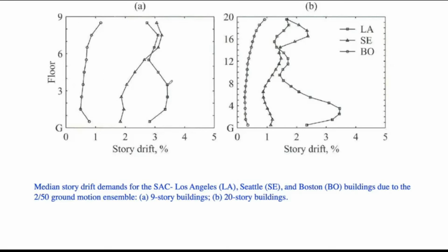Okay, so today's lecture was a bit shorter, and I completed it in one go using mostly plots and charts rather than going more into the theory. So I hope this will give you an idea of what is important when you are analyzing or designing inelastic structures. Of course, response history analysis is the most accurate procedure for analysis. And in the case of design, if you design a multi-degree of freedom system or a multi-story building, you should take into account the higher mode effect. One of the procedures presented here is that the base shear has to be modified for the multi-degree of freedom system, and that also depends on the fundamental vibration period of the structure. Also, understanding the statistical variations is very important for estimating the demands.